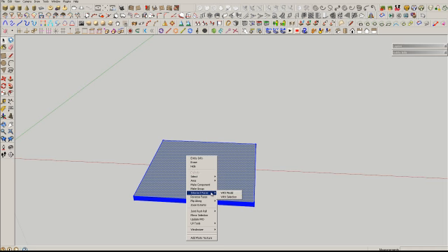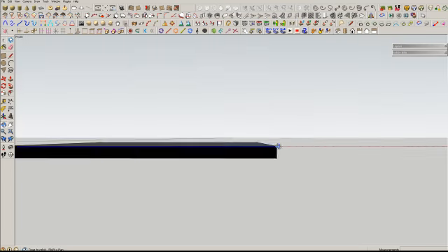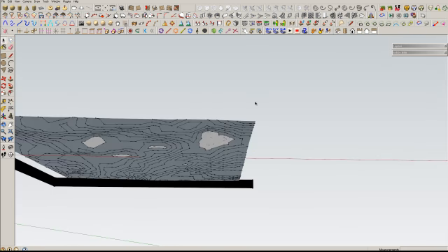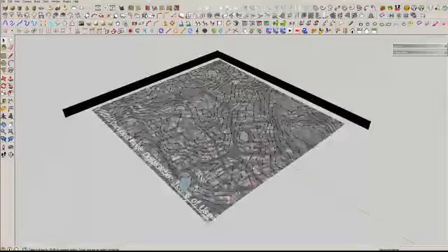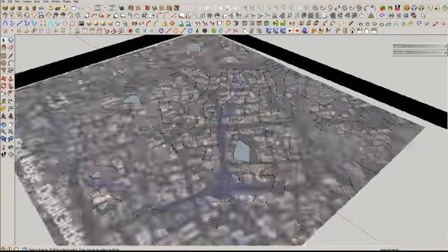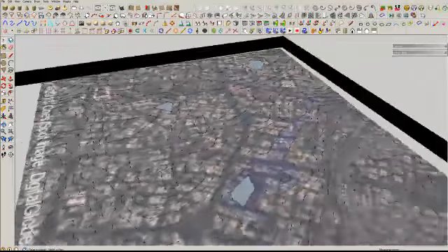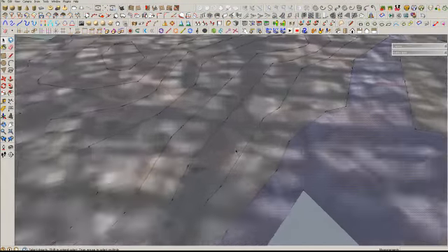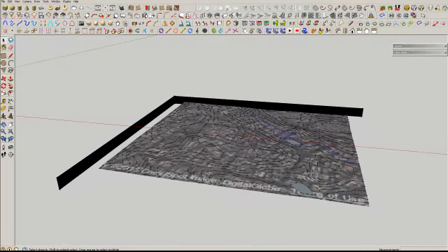So in order to get the intersecting planes, that is the contours, we go for intersect face, and then not with the model, but with selection, because we have selected this whole thing, right? What this is going to do is create the intersections. So you delete all of the surface, and this is what you get. And these are the contour lines which you'll be getting. You can basically fill them with anything, and these are the contour lines. And yeah, that's pretty much about it on how to create contour lines.